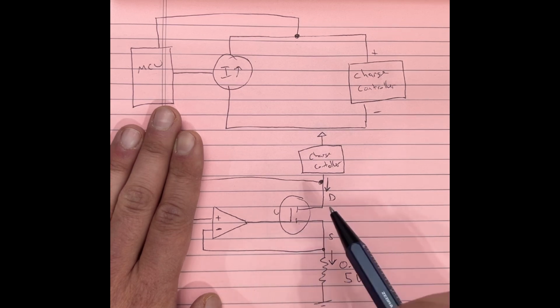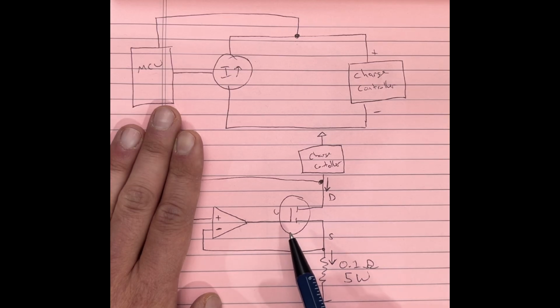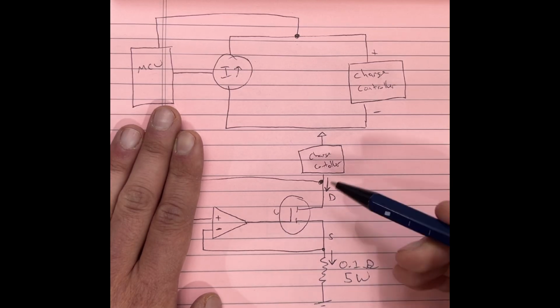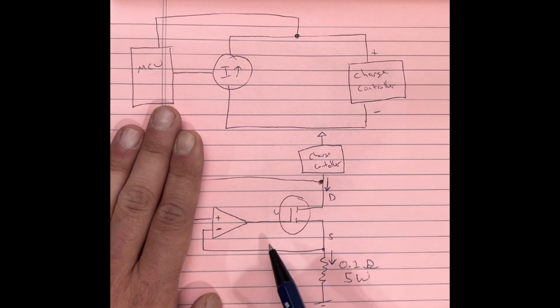This MOSFET here is just so I can basically drive more current through it than I could with just an op amp alone. So this feeds into the gate of the MOSFET. The MOSFET's set up in this source follower orientation. So, the voltage it gets at the gate, it will try to match at the source.